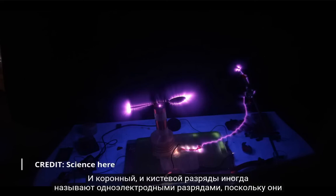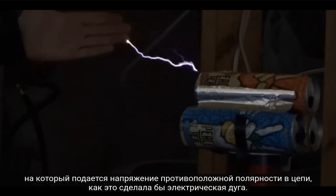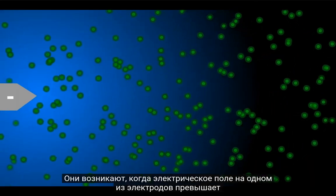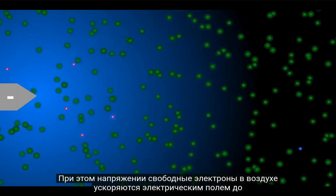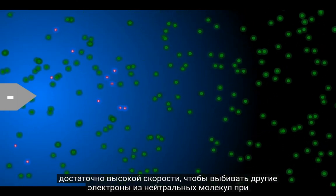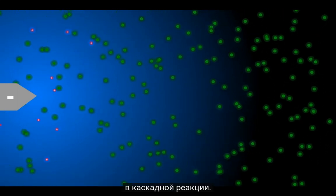Both corona and brush discharges are sometimes called one-electrode discharges, as they occur in the vicinity of a single electrode, and don't extend as far as the electrode carrying opposite polarity voltage in the circuit, which an electric arc would do. They occur when the electric field at one of the electrodes exceeds the dielectric strength of the dielectric surrounding it. Often this will be air, which requires roughly 30 kV per centimetre. At that voltage, free electrons in the air are accelerated by the electric field to a high enough velocity that they knock other electrons from neutral atoms when they collide, creating ions and additional electrons which go on to ionize additional molecules in a cascade reaction.